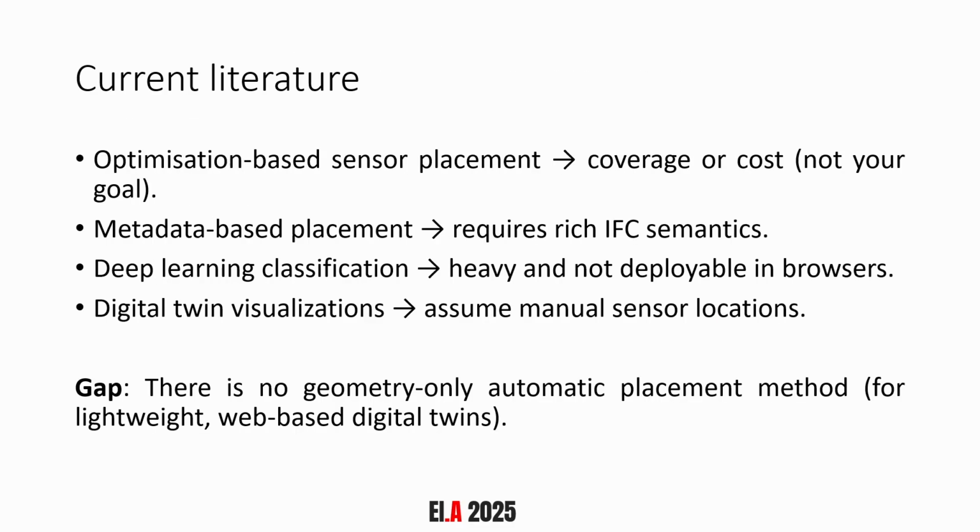We also looked at current literature. For example, we looked at metadata-based placements. Usually these are very academic, because they rely on very feature-rich IFC, which we haven't seen that much in the real world. We also have deep learning AI models, which are very heavy, and we kind of want a lightweight and more deployable way for embedded environments or browsers. So we see that there's a gap for geometry-only automatic placement methods.